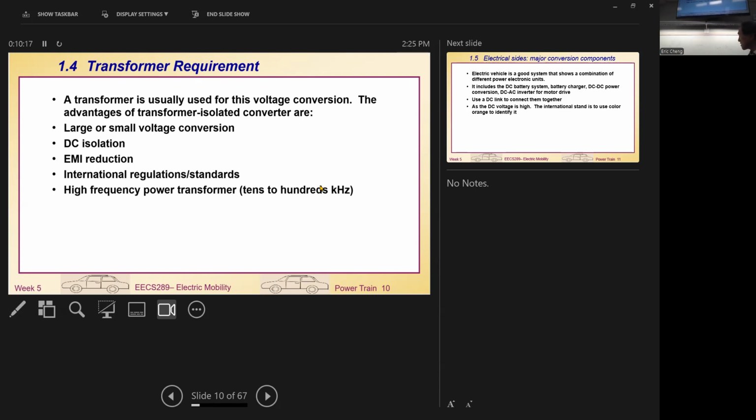So now, if using 60 Hertz, then that is the power, that's the inductance size. But if we don't use 60 Hertz, and we use 60 kilohertz for the frequency of operation, then this frequency is increased by 1,000 times. Then your inductance can be reduced by 1,000 times for the same power level. So if you use a transformer at 60 Hertz PG&E power level, but now we're putting it into high frequency power conversion, your transformer can be reduced by 1,000 times.